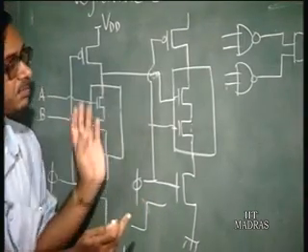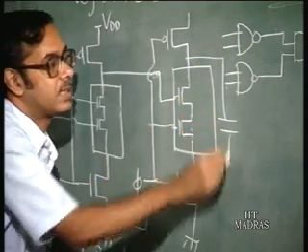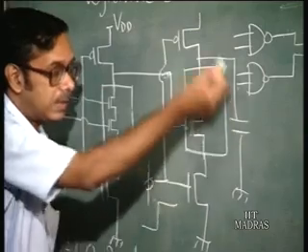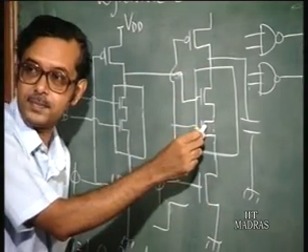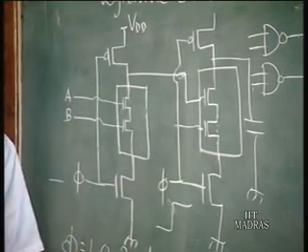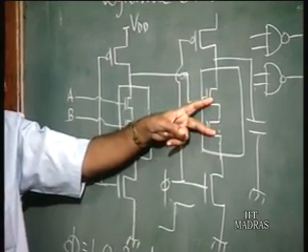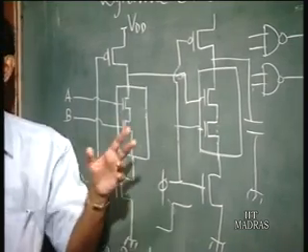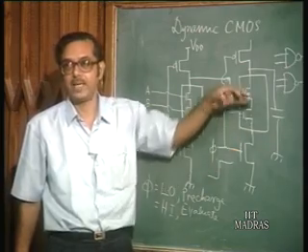Before it has time to react, in the pre-charge phase you have charged this capacitance. So, there is a path to ground immediately, because these transistors are all on. This capacitance is going to get discharged, because these inputs are all charged to high, all these transistors are on at the beginning of the evaluate phase. That is going to create problems, because once this charge is discharged, there is no way in the evaluate phase the output can go high.